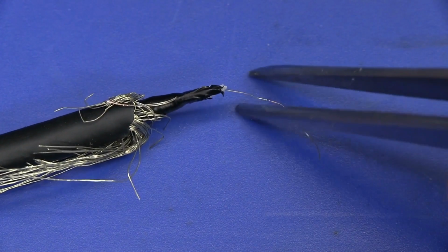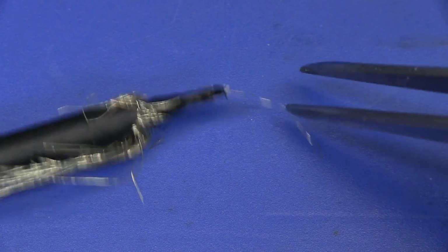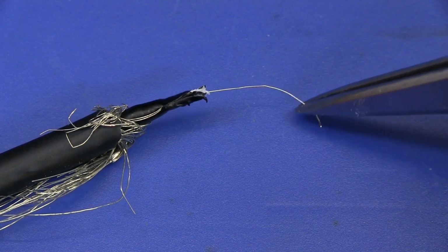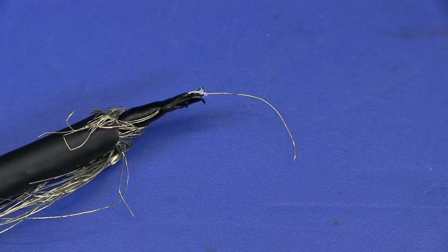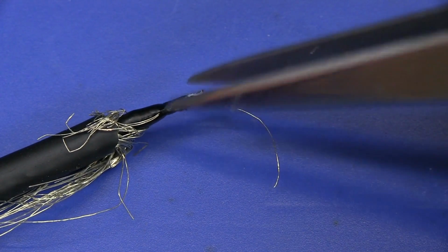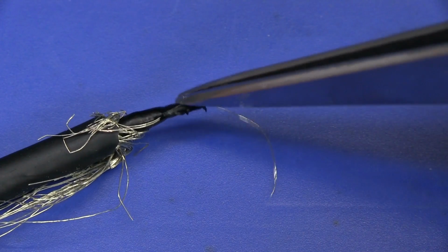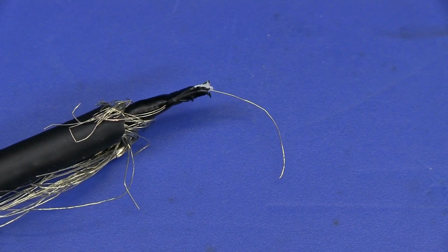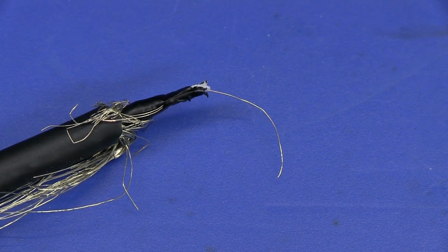Remember, this is only a 60 megahertz Velleman heap of crap. And that's what these probes are optimized for. They're optimized for their times 10 mode, the high bandwidth mode, which is why they are going to use this lossy transmission line, which typically, most probes are going to have a couple hundred ohms. It will vary by plus or minus a couple of hundred.